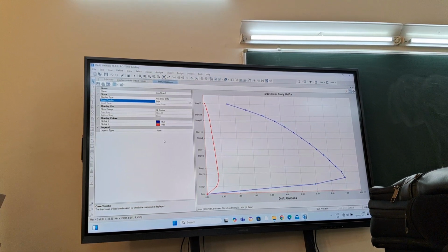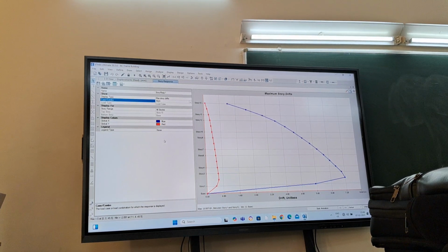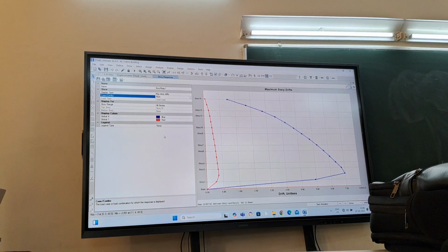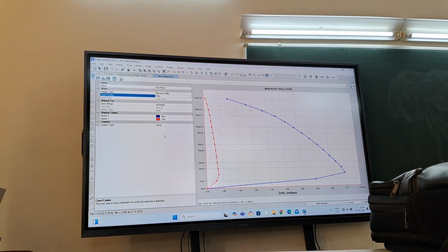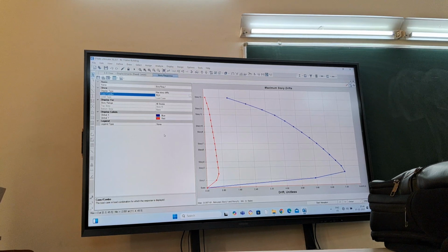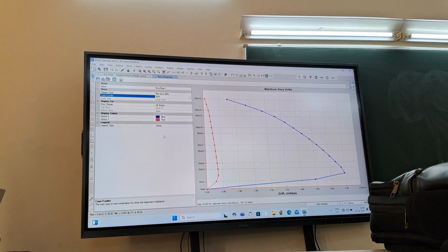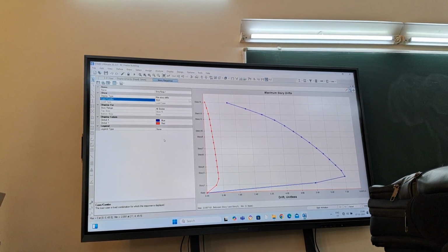That is why we scale our response spectrum forces by a factor to match the static load case. But when you are checking the drift, it will be governed by the response spectrum, not the equivalent static. Because if you plot the displacement spectra, as you have seen in your assignment, the period is longer. So the response spectrum load case will give you the higher displacement.